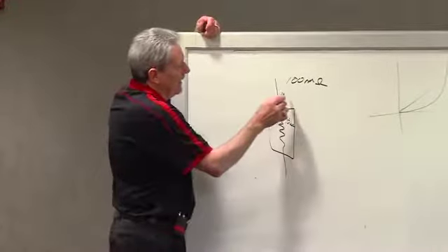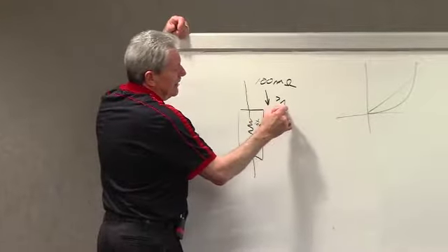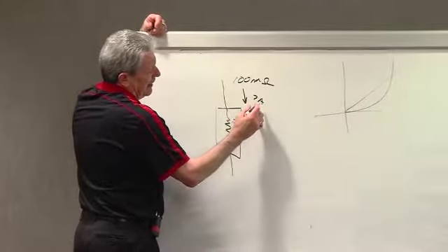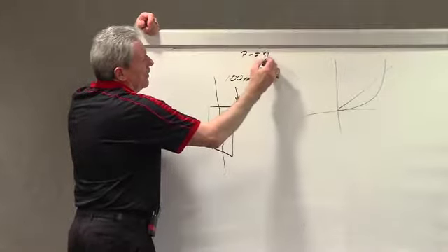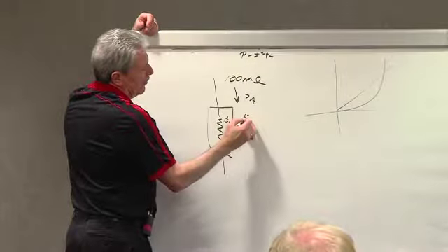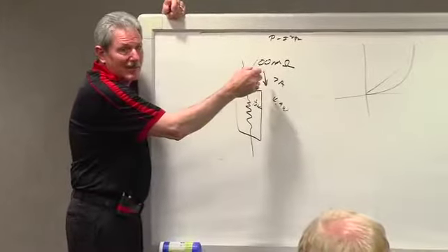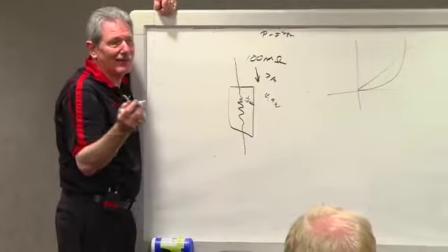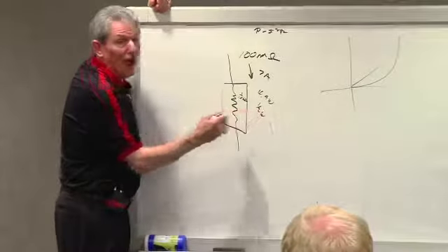So if I have 7 amps, going back to that same 7 amp, 7 watt, power is equal to I squared R, so this is 49 times 0.1, which is 4.9 watts. And 100 milliohm is high. Today we've got 10 milliohms, which would take it down to 1/2 of a watt.